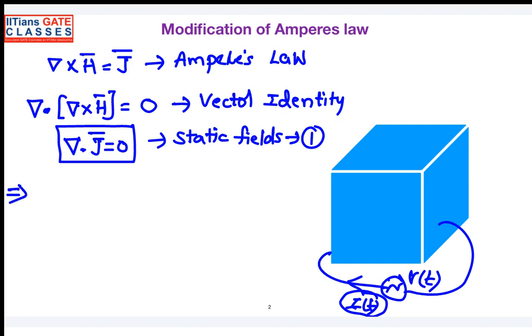So how do we define the variation of that current? The basic definition for current is the negative rate of change of the charge with respect to time. The negative sign indicates that the charge decreases with increase in time. That is the basic definition for the current. Now we will use the same equation and write the current in terms of the current density. We have seen in the types of current distribution that the current I can also be expressed as the double integral J dot ds.